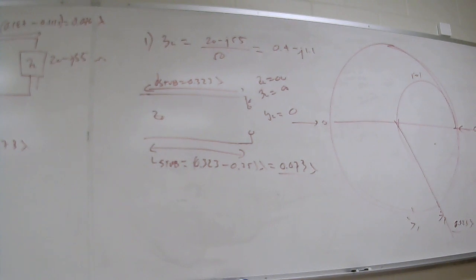Either you want to minimize this length that I just talked about. So if you want to minimize this length in the admittance domain, you want to go the shortest distance to this point or this point. You all with me? Now, if your load happens to be here, then it would make sense to move to here. But if your load's out here, it would make sense to move to this point if you want the line, this distance from here to here, to be minimum. Y'all hear me?